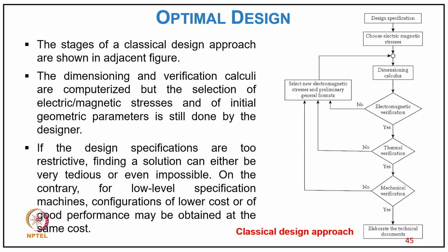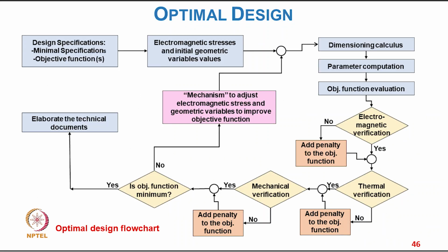Design specification, choose the electrical and magnetic stresses, then go to dimensioning calculation, then electromagnetic verification; if yes, then go to thermal verification; if yes, then go to mechanical verification; if yes, then elaborate the design. If no, select the new electromagnetic stress and preliminary general format.